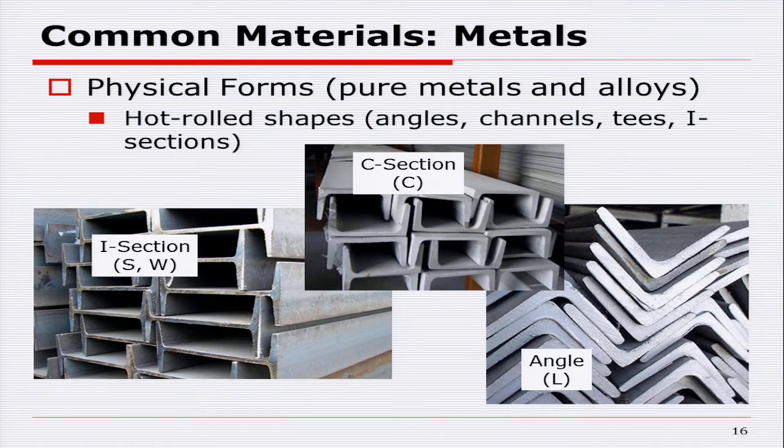The nice thing about angles, now we can make angles, and we do this a lot down in our shop. We make angles out of sheet and plates. We shear a strip out, and then we bend it, and we can make this same shape. But again, if we've sheared it out, it's going to have sharp edges on it right here. And when we bend it, we may not get it exactly 90 degrees. Again, it's not hard to get it close. But this thing is going to come perfectly 90 degrees, and it has those rounded edges on it. It's going to cost more for you to buy this than it would for us to make that angle out of a piece of flat sheet stock.